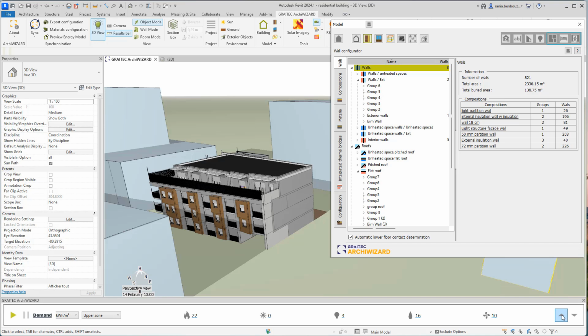So for example, the currently chosen configuration is a new concrete-based residential building. Since it is a new construction, ArchiWizard will fill in the composition with concrete elements that are insulated with a certain thickness. It is then up to you to accept those compositions or to change them if you have something else in mind. So for the purpose of this study, I'm going to open the envelope composition. To do so, I'm going to click here and you should see this tab generated.